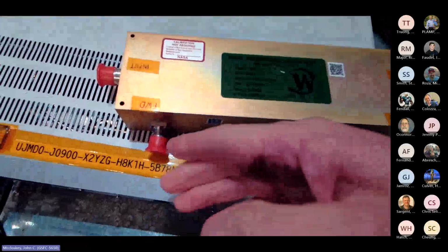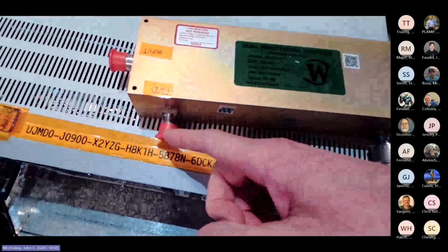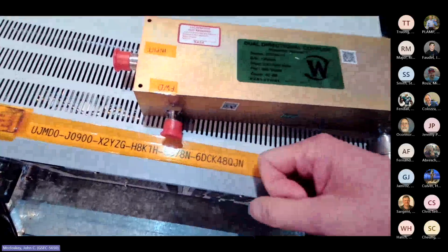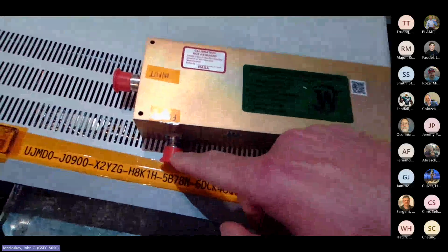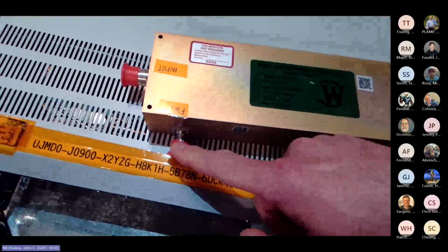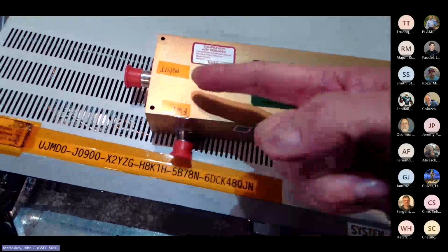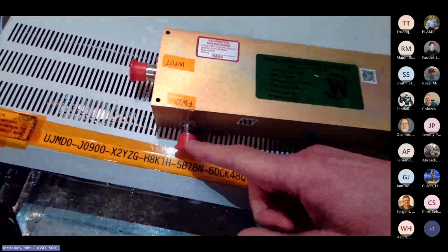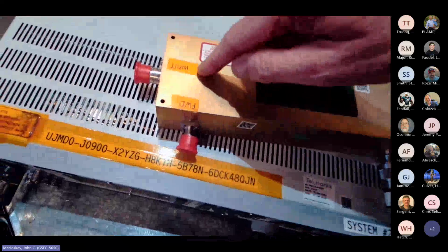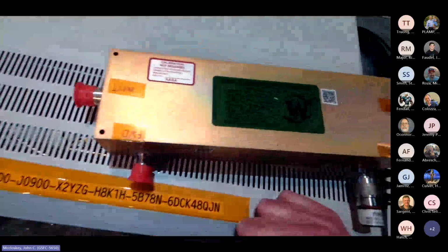So if you're monitoring on that and controlling on it like you would be with CS114, you just need to take into account that what you're seeing here is 40 dB down from the real signal. So you'd add 40 dB to it to get to what you're actually interested in.